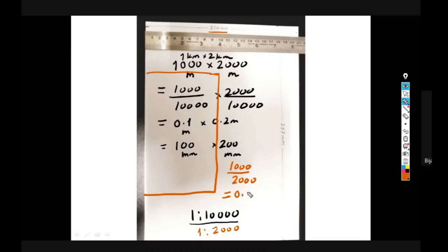0.5 meter by, let's say, 1 meter, right? 1 meter means how many millimeters? 500 mm by 1,000. Okay. So can I fit this? Because my width is 210 mm and it is asking for 500 mm. So it cannot fit. What can you do? We have to reduce the scale. Either you should divide the scale, let's say go to 5,000 or 10,000, or what else can you do? Change the paper size. Increase the paper size. Yes, increase the paper size.